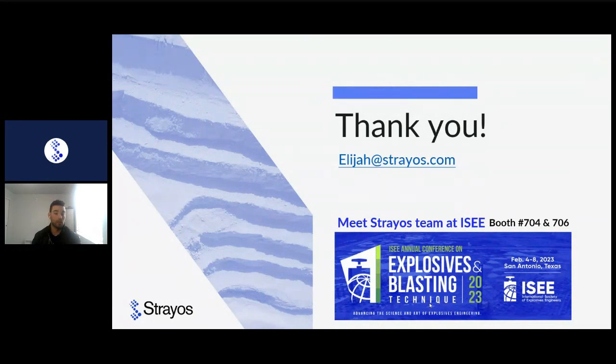Yeah. So importing borehole probe data into Strayos, it's fairly easy. You gather your information, plug it into Strayos, and it'll give you that real-time 3D burden measurement and profile.